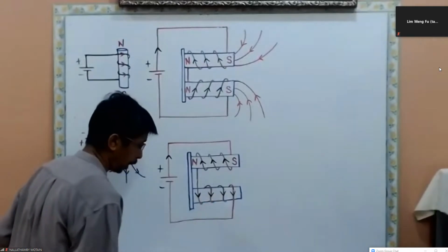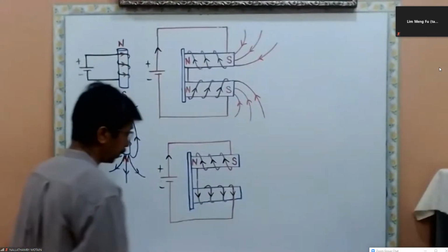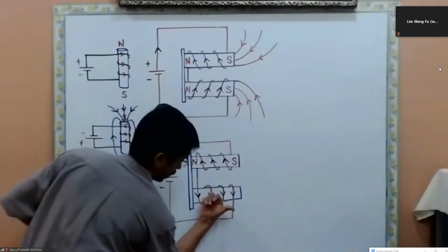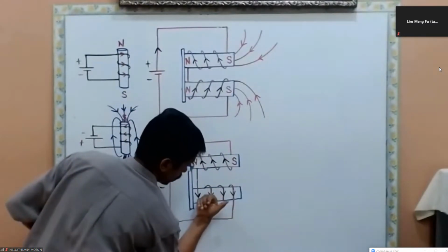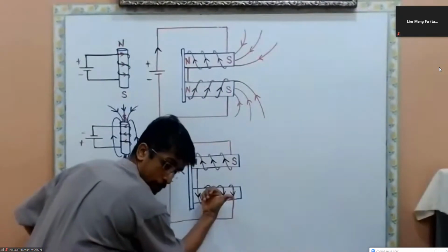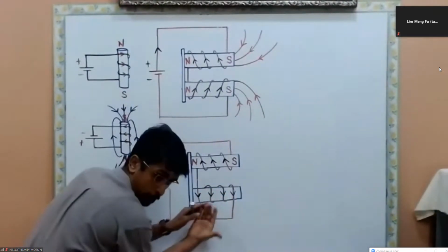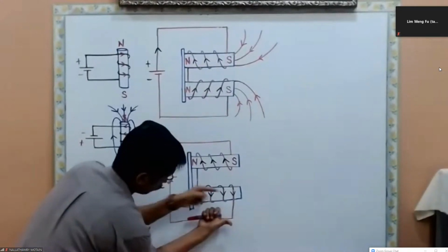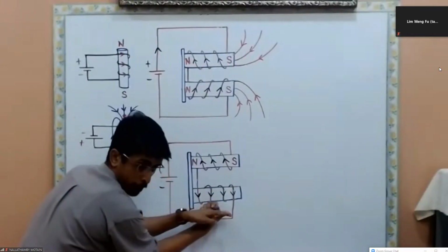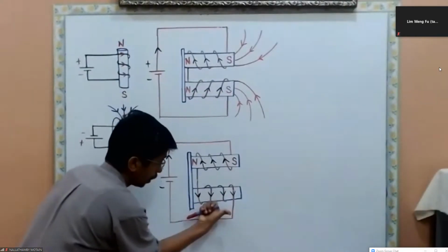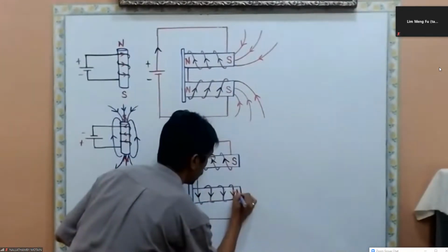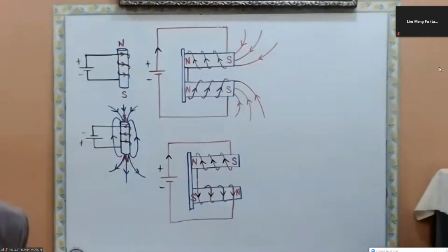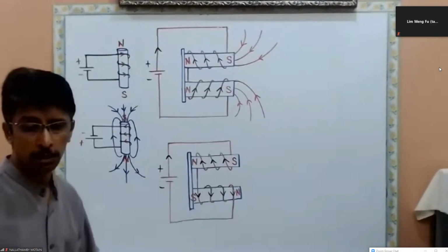Then come to second core. Where is the poles? Okay, here current is moving downward, correct? Come to the front, in front, downward, and then your thumb points to the right. Okay, check again. Current in front, downward. Yeah, so see the 4 fingers over here. Follow the direction of the current, and then your thumb points to the right. So here will be north pole. Here will be south pole. Okay, one end become north, one more end become south pole.